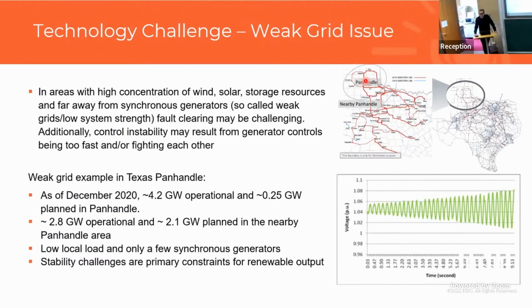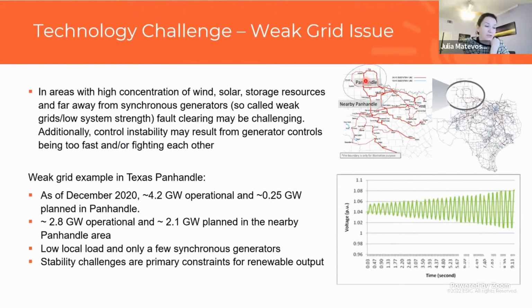Any other question? Yeah, but also, the disadvantage with synchronous condensers is that you need additional equipment, whereas what we're trying to show in the study is that if you equip batteries that are already going in as resource with grid forming controls, they can provide the same support, but you don't need this extra kit. So yeah, there is economic benefit in that as well.